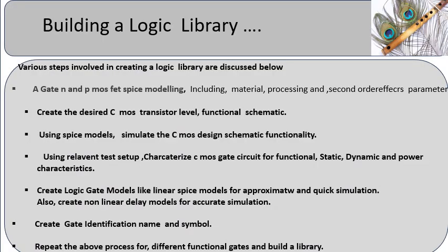Various steps involved in creating a logic library are discussed below. Identify appropriate MOSFET SPICE models, that includes relevant material, processing, parasitic and second-order effects. Using SPICE syntax, create desired CMOS transistor level functional schematic. Using SPICE models, simulate the CMOS schematic for functional verification.